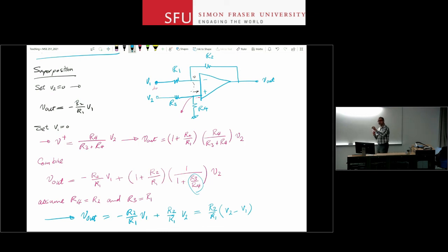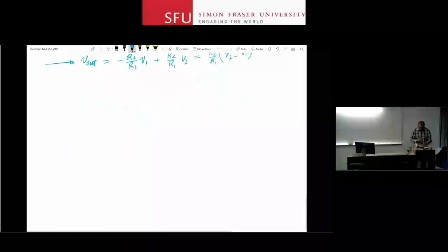So you have asymmetry between the two inputs. And even if your V1 and V2 are exactly the same with the same output resistance, they will see different input resistances when they look at your difference amplifier, and that affects the output of your circuit. So to go around that problem, we improve this circuit by adding a couple of buffers to it.